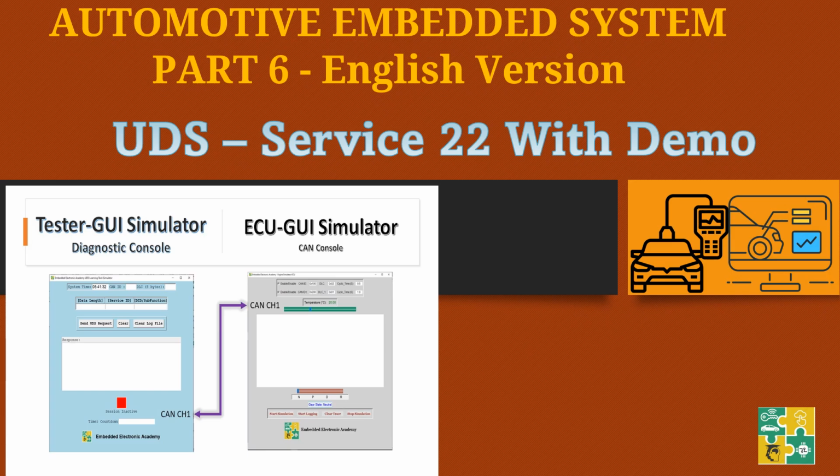In a real system, the data exchange happens over a CAN channel, but here we are exchanging data in the file system. So some information is written into a file, and the same information is read by the other simulator via the file system. But if you see the overall picture as a demo, it will look like how a real ECU will work. The same method will be there.